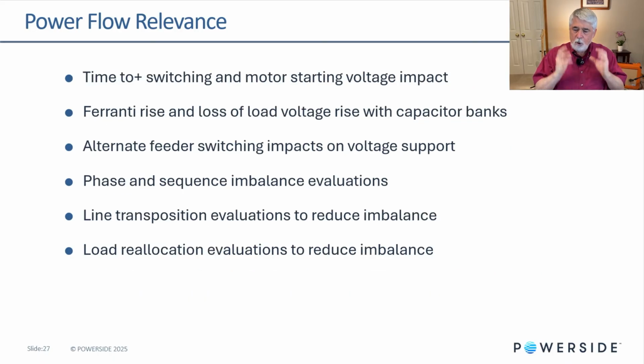One of the most key things that I've actually used myself is time T0 plus switching. In this case, you need a slightly modified power flow solution that replaces the swing sources, voltage controlled sources and motors with Thevenin equivalent voltage sources. If you have a tool that allows you to do that, then you can simulate that moment right after the switching event, whether it's starting of a motor, switching on a capacitor bank, or a sudden loss of load event. You can determine what that sudden voltage change is by doing a time T0 plus switching event.